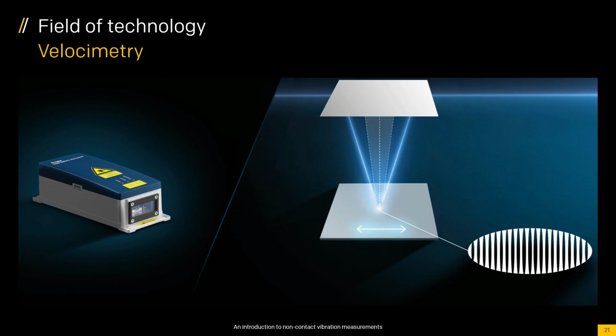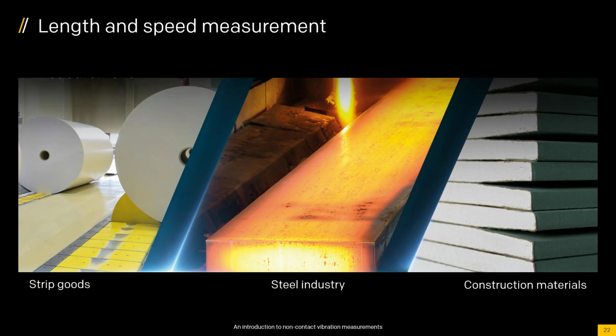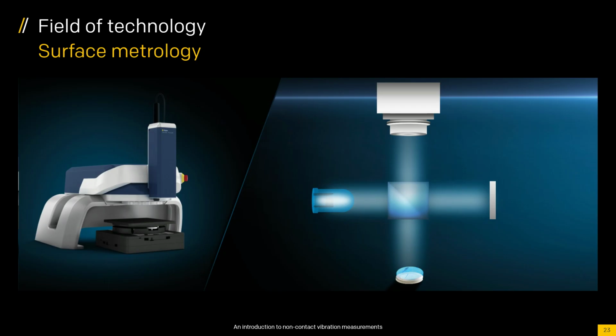So if your structure is moving at 500 hertz, and you are just really worried about the vibrometer, you just apply a 10 hertz high pass. It gets rid of all that stuff. Now, what if the vibrometer is moving in the same frequency range as your frequency of interest? Now we have to do something. So there are all kinds of tips and tricks that we can play with.